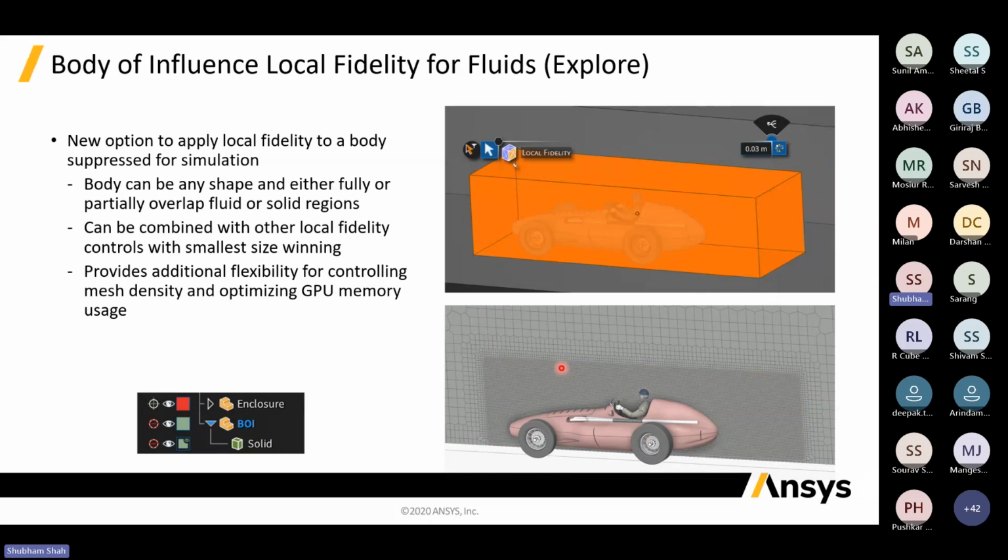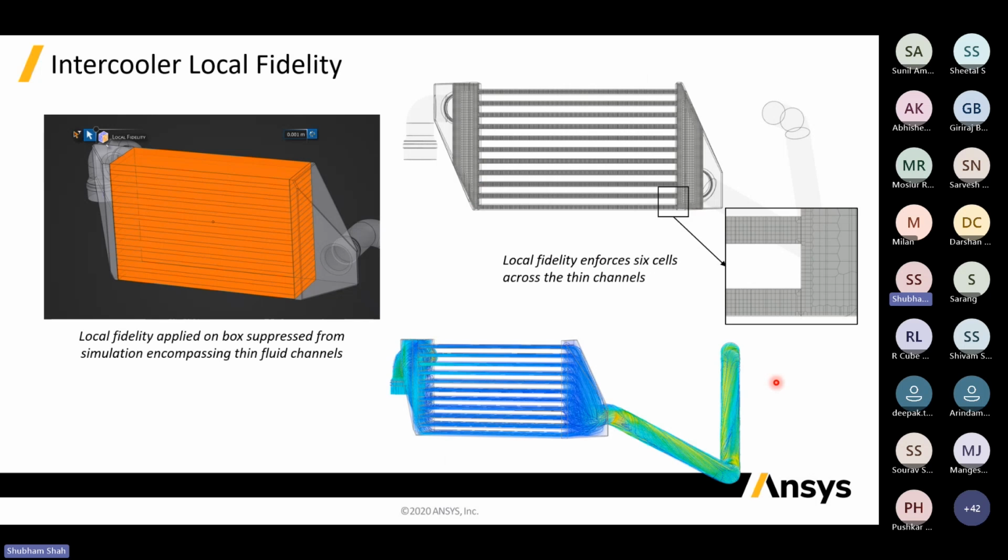Basically it's added in the refined mode, and we can see how the refined mesh is available now. Earlier this was only available on the Fluent side, the refinement of meshes and everything, but now this is added to Discovery as well. These are a few examples for the local meshing. You can see over here how the local mesh can be done.